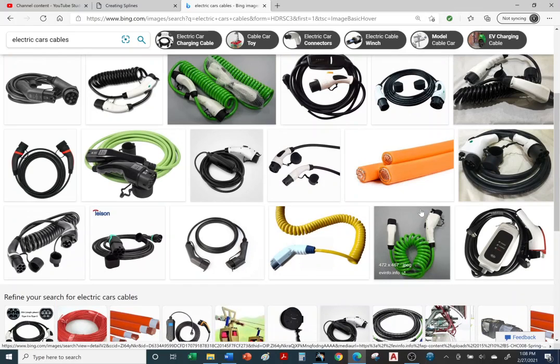So when you see an electric vehicle, if you look under the hood or near the charging unit, if you can somehow get in there and look, they have these high voltage cables. Typically, it should be covered in orange. I believe that's standard that we follow here in the US. I'm assuming also the other countries use the same color. So this color is telling us that this is a high voltage cable. In this case, it leads to the charge port where you connect your charging component, right? And these are thick. These are around 13 or 14 millimeters in diameter, which is more than half an inch in diameter. Okay.